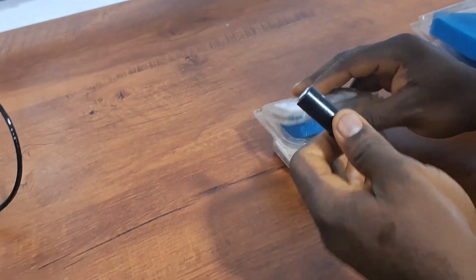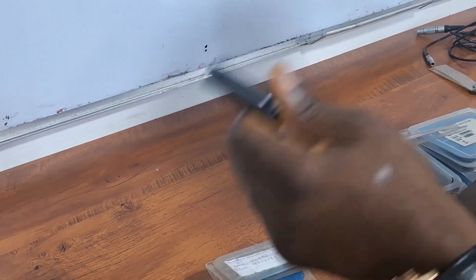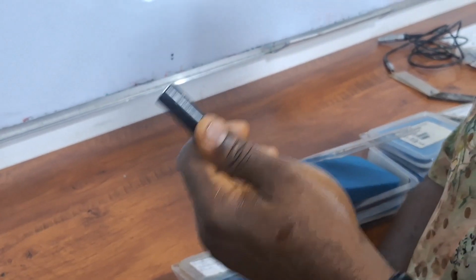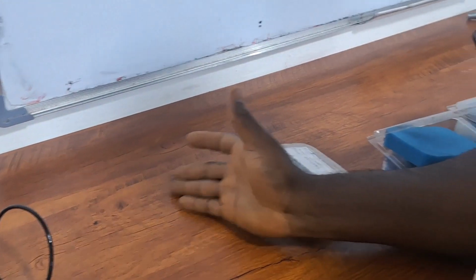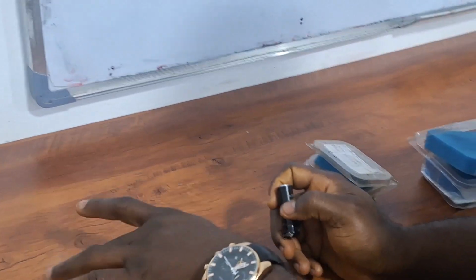One major difference you find between a surface probe and a weld probe is the frequency. The surface probe usually has very low frequency compared to the weld probe, because you are scanning the surface, just looking for very tiny cracks.